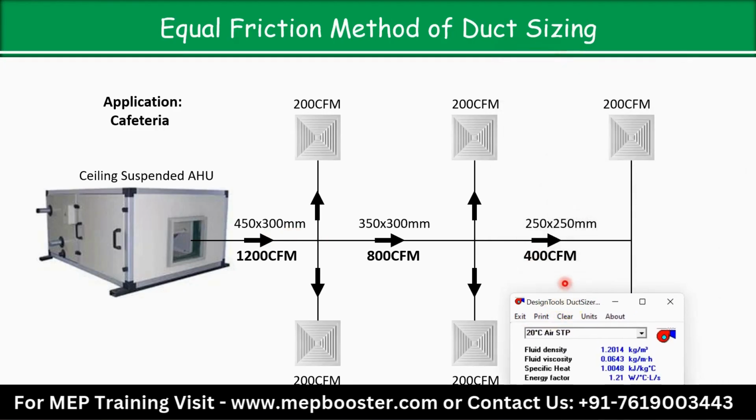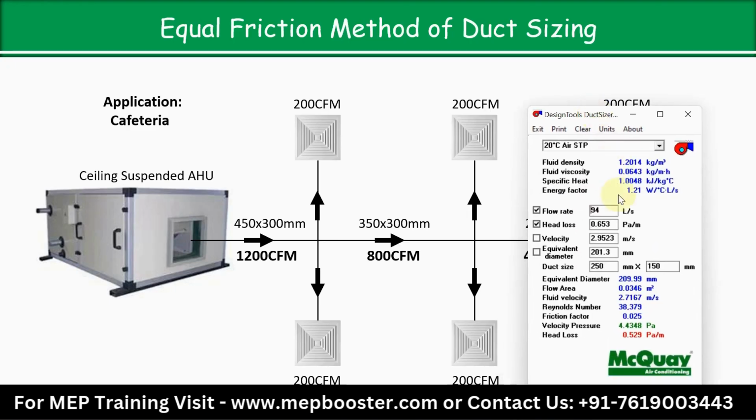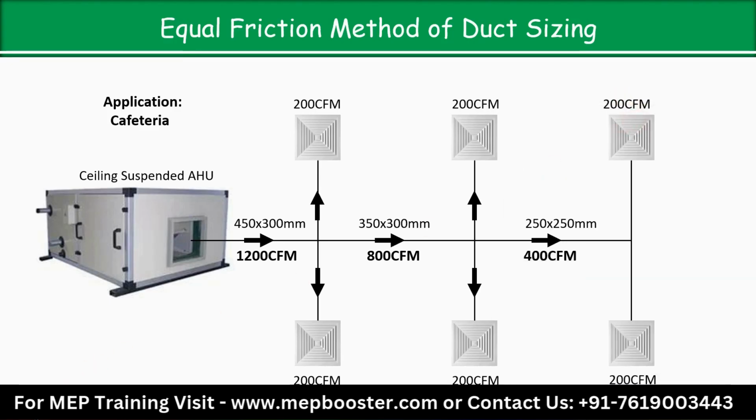But the problem is that for 400 CFM we reduced the height to 250, so for this branch duct 250 is possible. But when you are connecting these two branch ducts, better is to take the height 200. As per that you will get the value 200 by 200 for the branch duct. Is it clear?